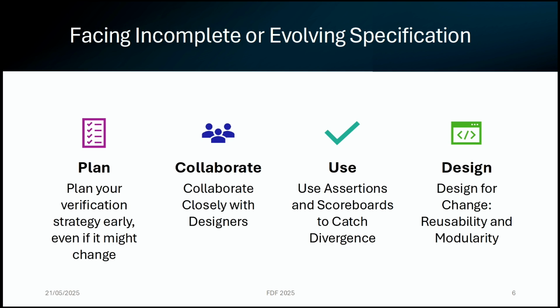And then now we move to a bit of a more technical part. That is, use assertions like living spec. Assertions in your design can behave really like living specification, because specification might keep evolving or might be incomplete. But when you write a property into the design, that property must be coherent with the design behavior.